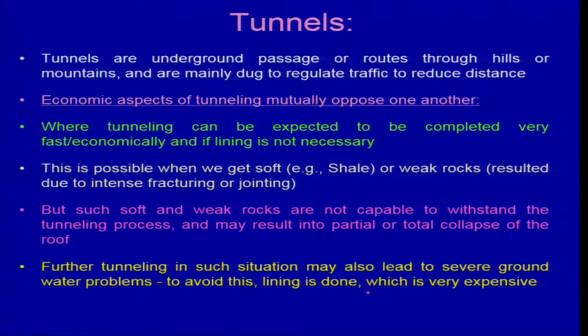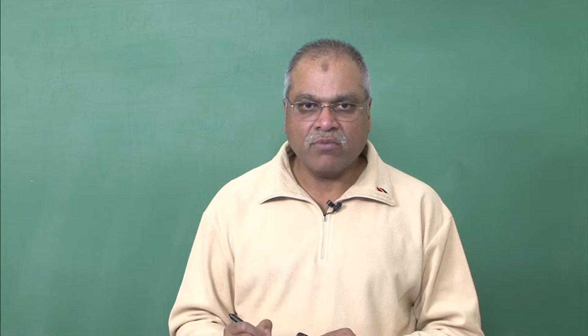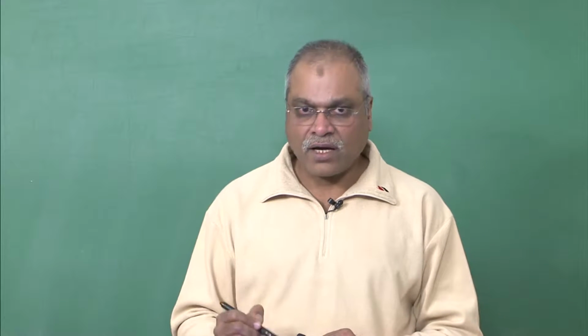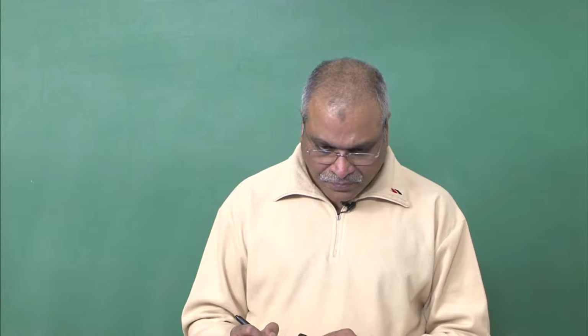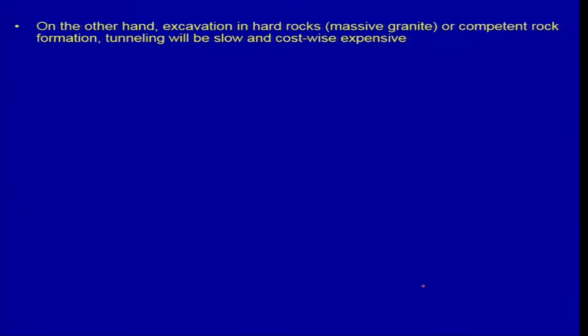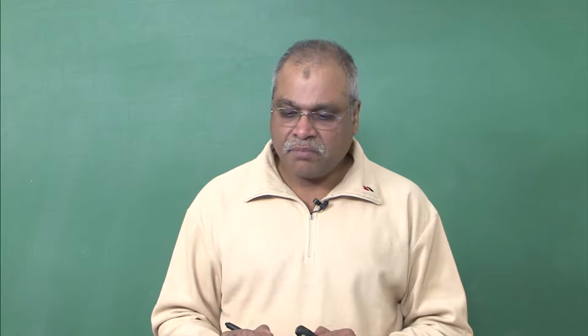So you want to do the project in a much quicker sense, but at the same time, because you are excavating in softer rocks, you may face these problems. You may have collapse problems, you may have a lot of water seepage problems. And that will end up in more cost for the project, because you have to put in the lining and all that. On the other hand, excavation in hard rock, because you want to avoid the collapse, you want to avoid the water seepage and all that.